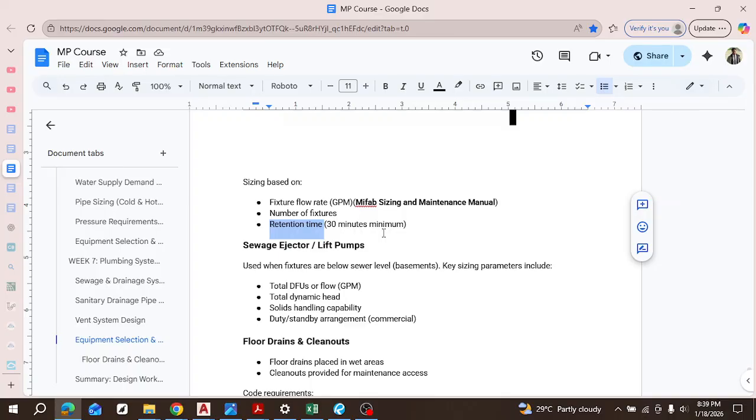When the liquid settles, it is able to separate better. But if it flows in and it's still turbulent and does not settle down, it's likely to also flow out. A lot of grease is likely to flow out too. There are some that will tell you sometimes you can also size with 1 hour, or even more, right? But it's usually around 30 minutes or an hour.